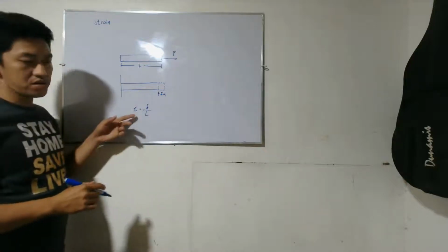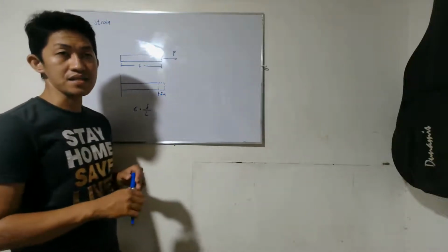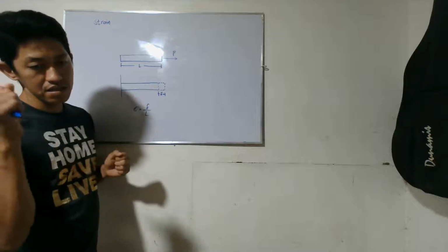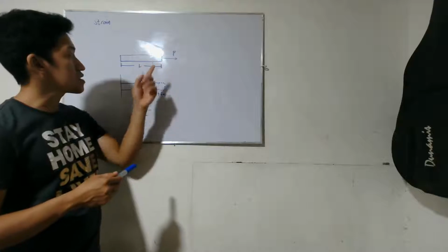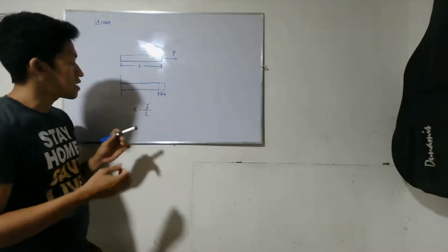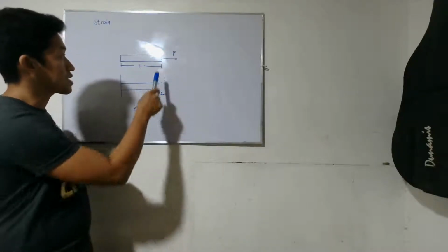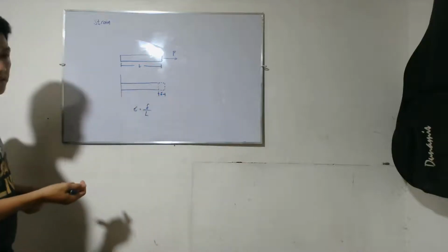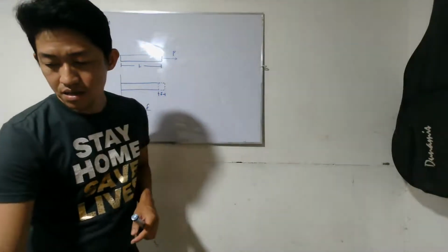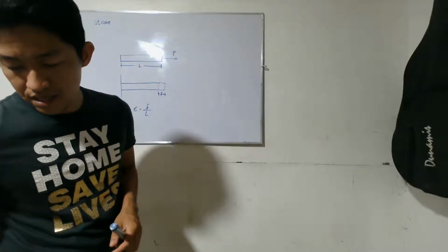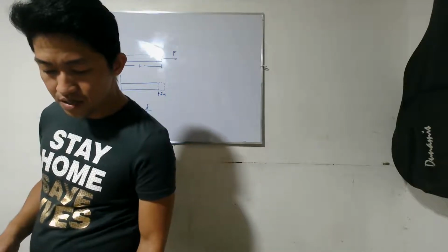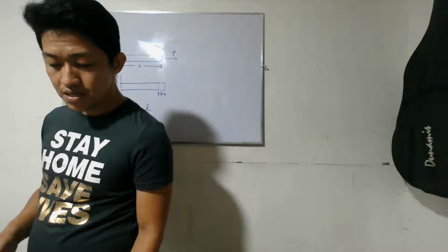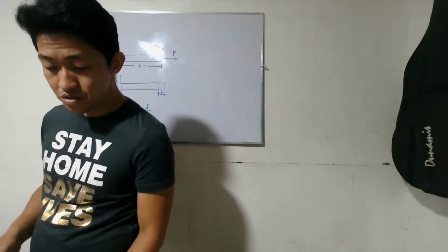Okay, or strain in other words is just the percent deformation that is experienced by the body as it is being stretched by this force F. Okay, so we will talk about axial strain and also the shearing deformations, axial and shearing deformations.